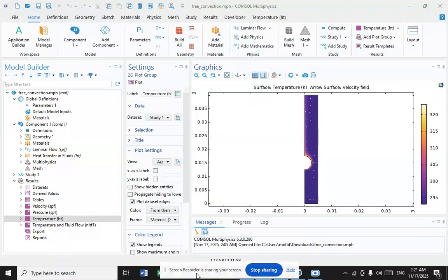The pictures of free convection development in the flow past a hot sphere or horizontal cylinder are qualitatively similar. On bodies of large diameters, a turbulent boundary layer develops, thus forming an ascending turbulent thermal plume in the trailing edge. From hot bodies of small diameters, a laminar thermal plume ascends, which at some distance from the body becomes turbulent.